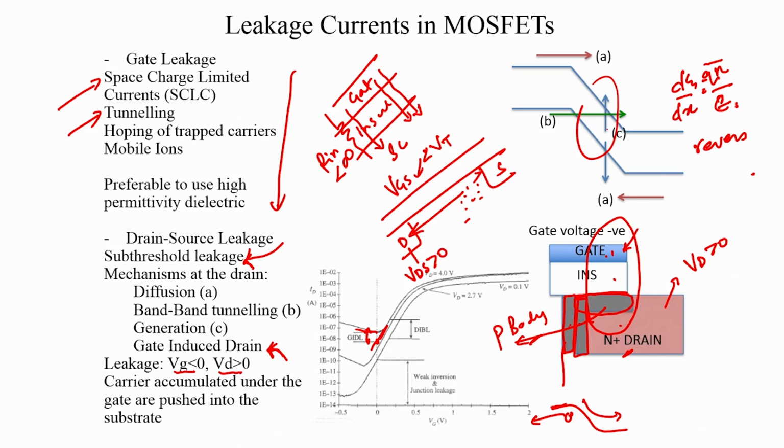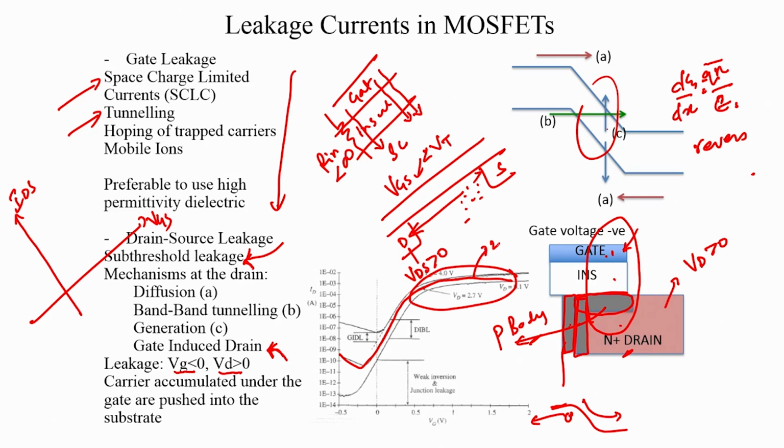Now, why are we so worried about leakage? So, firstly it completes our MOSFET models, right. So, we looked at, let us draw the IDS VGS characteristics of a MOSFET. So, we now have a characteristic which is actually very well drawn here. So if you look at this characteristic, we initially had defined models for only the above threshold region, which is all your square law characteristics.